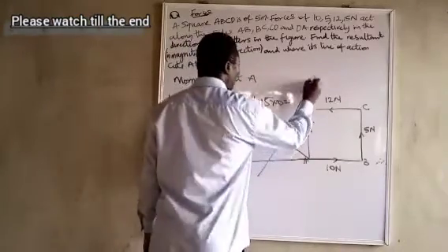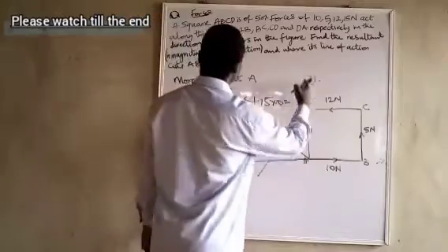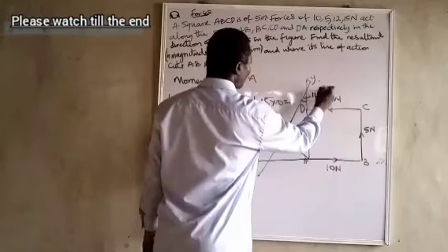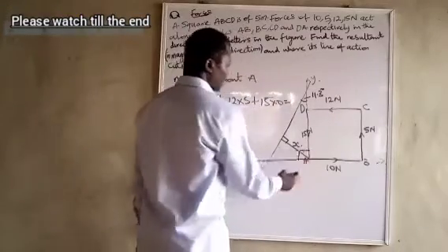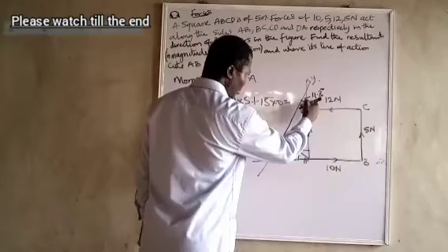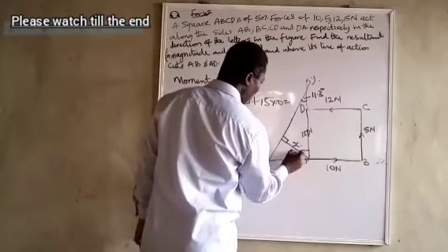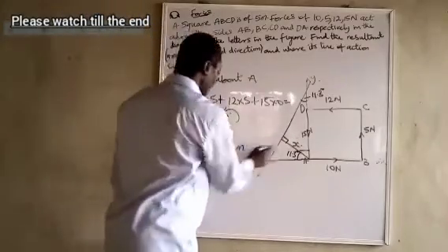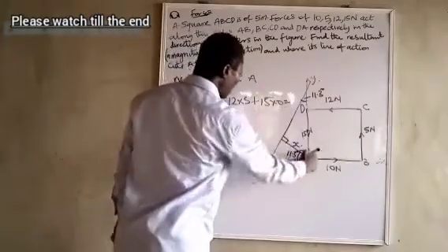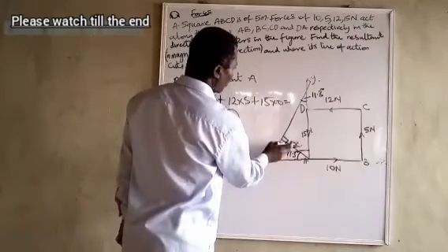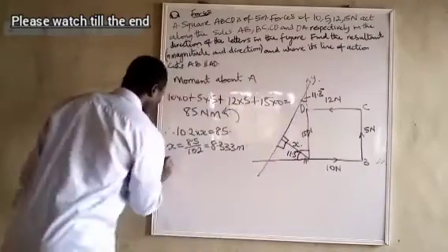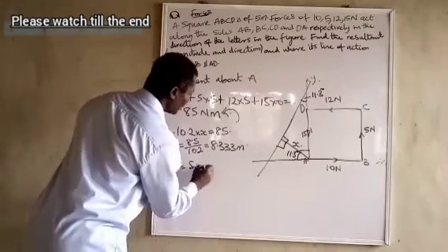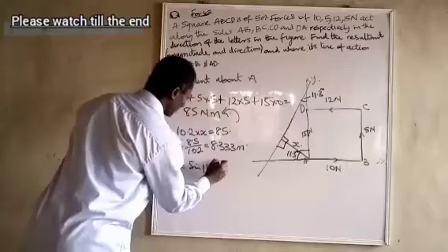And now we are asked where it cuts AB and AD. I have known that this angle is 11.3 degrees. Since this angle is 90, I know that this other angle is going to be 90 minus 11.3 degrees. So this place too is going to be 11.3 degrees. You can see this place and this place, they are equal. Now, I have known what this place is, 8.33 meters. I want to find this place and I want to find this place. Now, this is opposite to this side. So, AY over x is equal to sine 11.3 degrees. I work that one out.